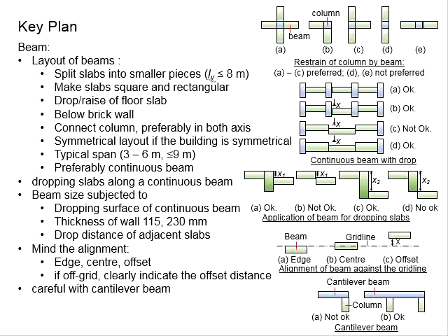Or if you see the reinforcement bar over-congested within the beam, that means most likely the size is relatively small. You're going to require a lot of reinforcement bar. Probably you will need to use a bigger size. As far as the key plan is concerned, especially during the first round you propose the key plan, it will govern your analysis later.